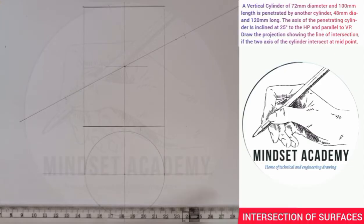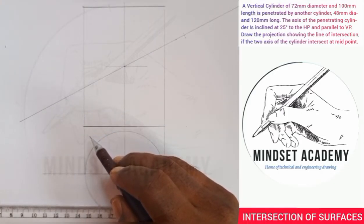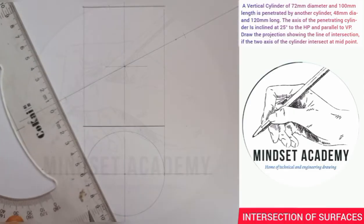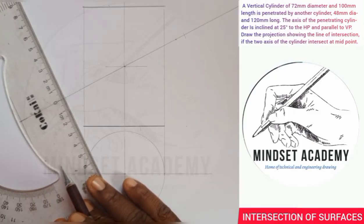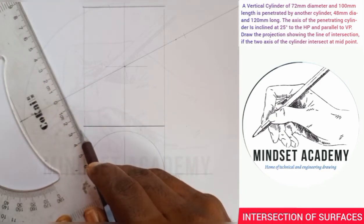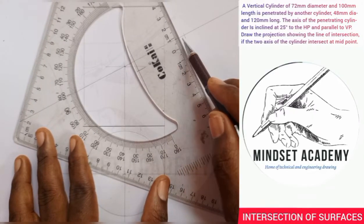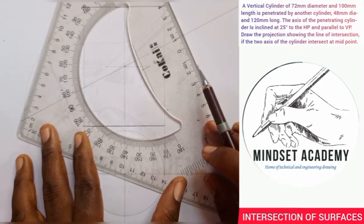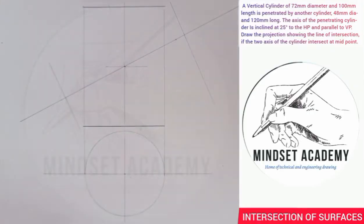So in doing that, at this point here, I'm going to draw a line at an angle of 75 degrees, or you just take your protractor and ensure that your line is coinciding with that line. Ensure that it's forming 90 degrees with that line. Once I've done that, I'll draw a line this way. Can you see it is 90 degrees here? I'll come here also and do the same thing, ensuring this longer line is aligning with that line. So they are forming 90 degrees.